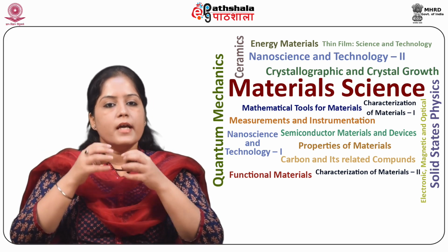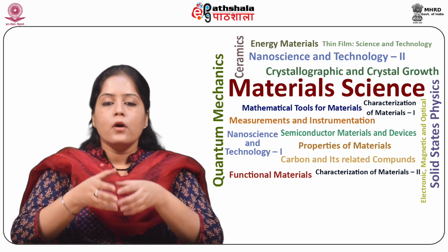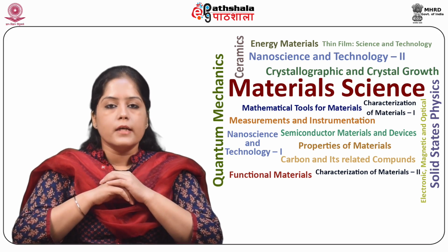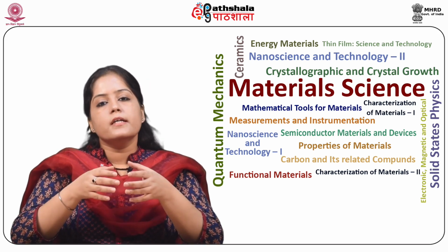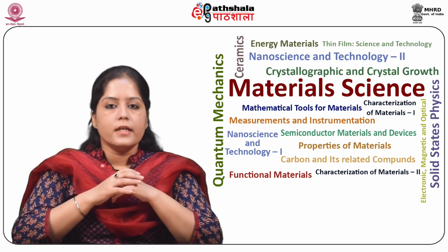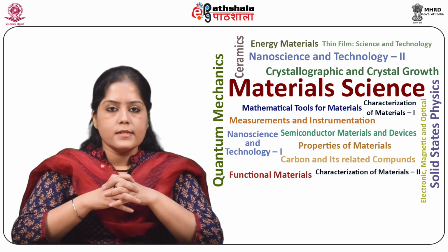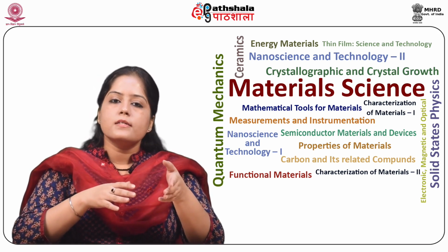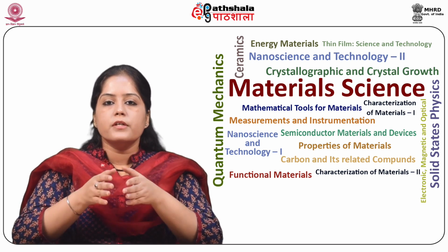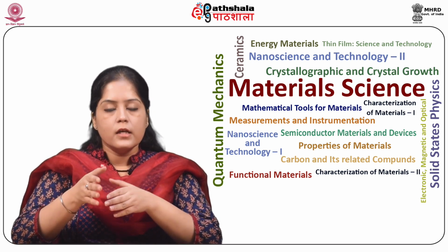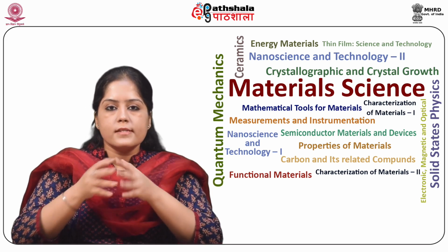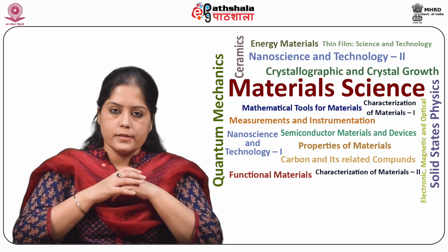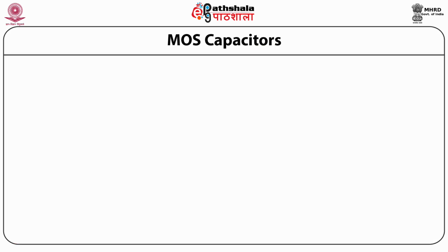The metal or heavily doped polysilicon of the MOS capacitor in a MOSFET is called the gate. Accordingly, the metal or polysilicon electrode of the MOS capacitor will be referred to as the gate, and the oxide will frequently be referred to as the gate oxide to distinguish it from the oxide layers that play other roles in integrated circuits.